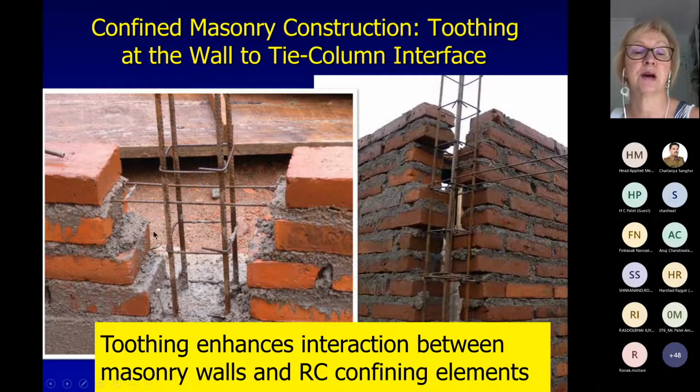Here you can see, for example, how small is this cage, reinforcement cage, because if this wall is 110 centimeters thick, so the cage is much less than 10 centimeters. And you can see that same building, how the wall, and you can see that leather reinforcement, how it is sticking. They will cut it off later, I guess, and you can see that it is placed only at some locations, so it's maybe at 40 centimeters or 50 centimeters. So they had both toothing and that reinforcement for some reason.